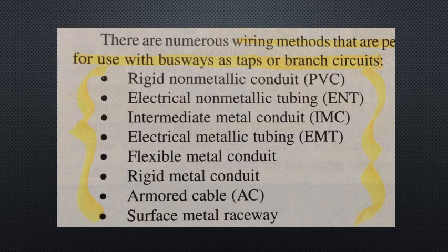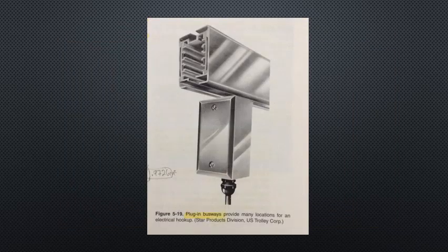Overcurrent protection. Overcurrent protection of busways is required at the supply end. If a smaller busway is tapped from a larger busway, overcurrent protection at the tap point should protect the smaller busway. An exception allows a short tap, 50 feet or less, with an ampere rating of at least 1/3 that of the overcurrent device protecting the larger busway, to be exempt from the required overcurrent protection at the tap point.